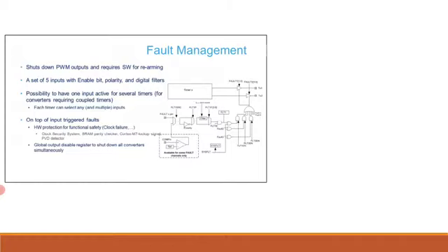The system errors indicate chip-level abnormal behavior such as a clock security system error, an SRAM parity error, a Cortex-M7 core lockup, or a potential brownout condition with the PVD detector. This helps to increase the functional safety level. Lastly, a global output disable register allows all the outputs to be disabled synchronously in a single write access for an emergency shutdown.